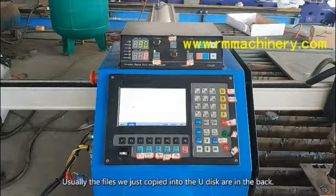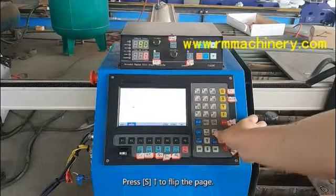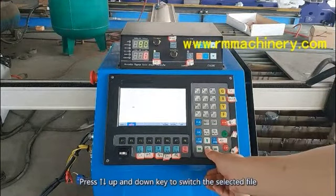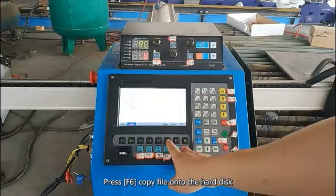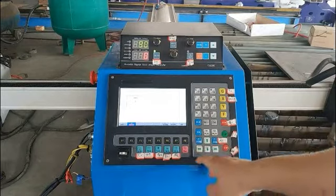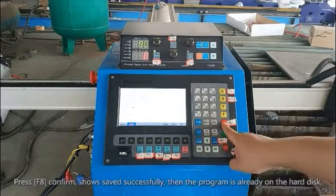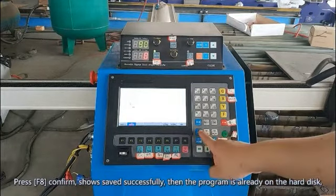Usually the files we just copied into the UDisk are in the back. Press S to flip the page. Press the up and down keys to switch the selected file. Press F6 to copy the file onto the hard disk. Press F8 to confirm, and it shows saved successfully, then the program is already on the hard disk.